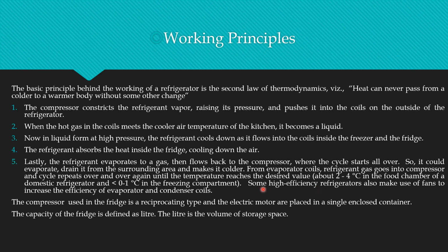degree centigrade. Some high efficiency refrigerators also make use of fans to increase the efficiency of the evaporator to condenser coil. A fan is used in the newer fridges, connected to the compressor motor. It will supply air to the condenser coil where the freon inside the coil gets cooled and converted to liquid.